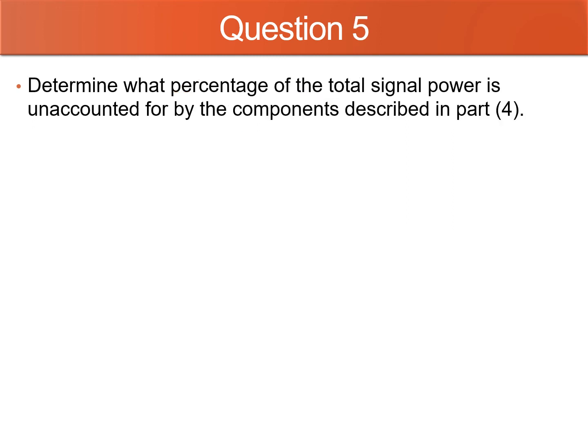Okay, for the last question, determine what percentage of the total signal power is unaccounted for by the components described in part 4. We know that the total power is equal to P0 plus 2 times P1 plus P2 plus P3. Substitute all the information that we calculated before.